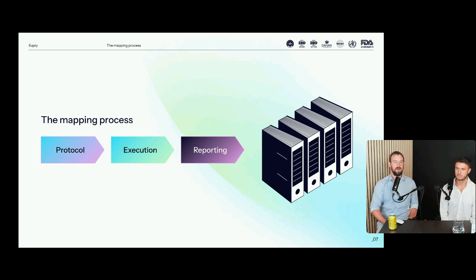So the mapping study report should be a starting point for defining your ongoing monitoring strategy. So how do you plan to use the data from that, both in terms of the standard operating procedures that you'll be operating the facility or the equipment under, but also where do you plan to place data loggers going forward.